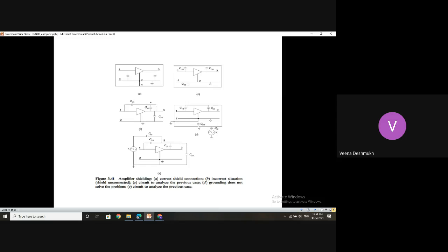And if this C2 is connected with one end here and the other end not connected, this causes this voltage Vi, which is produced across this. Now this Vi comes into the picture, and by connecting this Vi like this, whatever input comes here to the input end of the instrumentation amplifier is going to be influenced by these two capacitors.